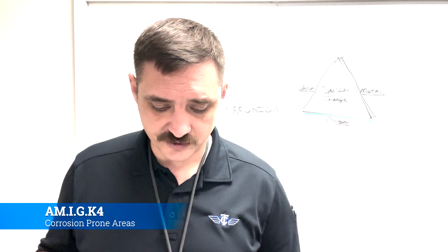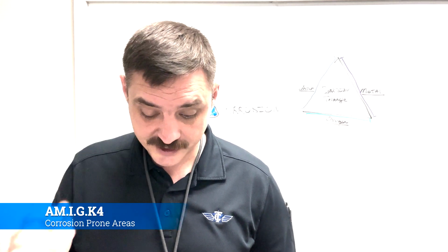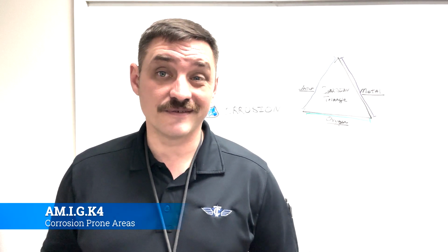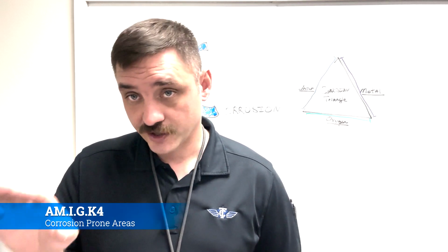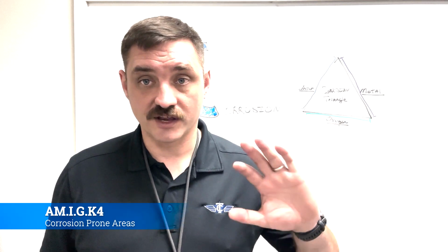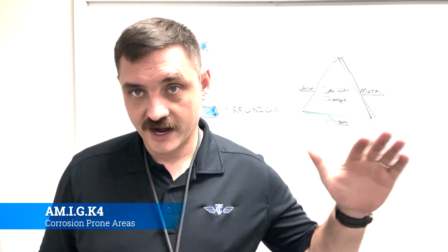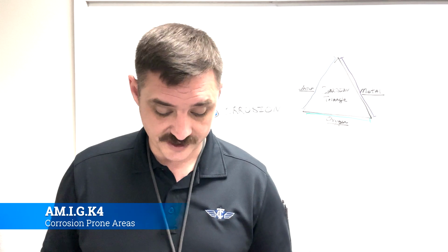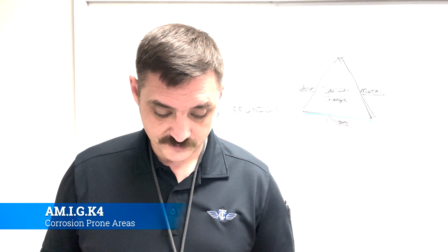External skin areas, external aircraft surfaces that are readily visible and accessible for inspection and maintenance. Even here, certain types of configurations and combinations of materials become troublesome under certain operating conditions that require special attention. So anything that is exposed, even a painted aircraft surface, can have corrosion. Whenever you're doing your general visual inspections, your GVIs, you're looking at rivet lines, and it's always good to look and then clean with your hand, like take a rag and run over the top of it. If there's any sort of corrosion, you will generally either see it or feel it, and it'll look different than everything else, and you'll know that it's there. But those are all areas where you could end up having corrosion.